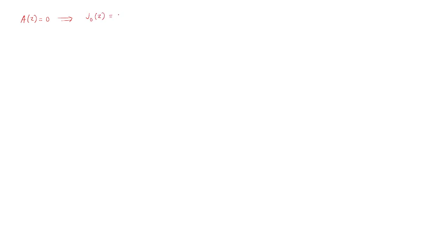Your J0(z) should be G1(-z), that is, your synthesis filter on the first branch should be the flipped spectrum of the analysis filter on the second branch, and the synthesis filter on the second branch, which is J1(z), should be the negative version of the flipped spectrum of the analysis filter on the first branch.